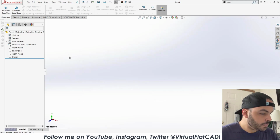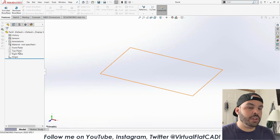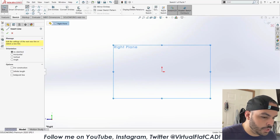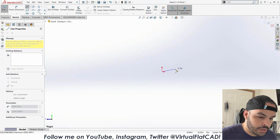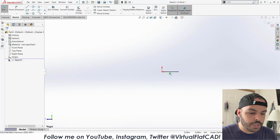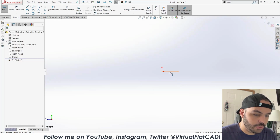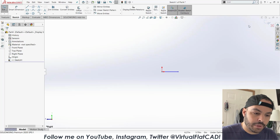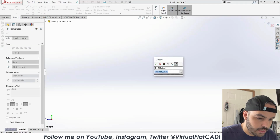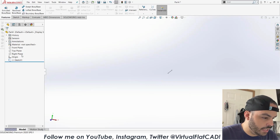So I have a new part here, and one of the things I want to do is get a helix, and I want it to project towards the side. So I'll first start with a line, which I know might be strange because usually in SolidWorks we start with circles, but I'm actually not going to use the helix tool, and the reason for that is the helix tool does not allow me to animate it very well. So let's get a length on this thing. Maybe 1 inch like that. I'll leave it under define for right now.